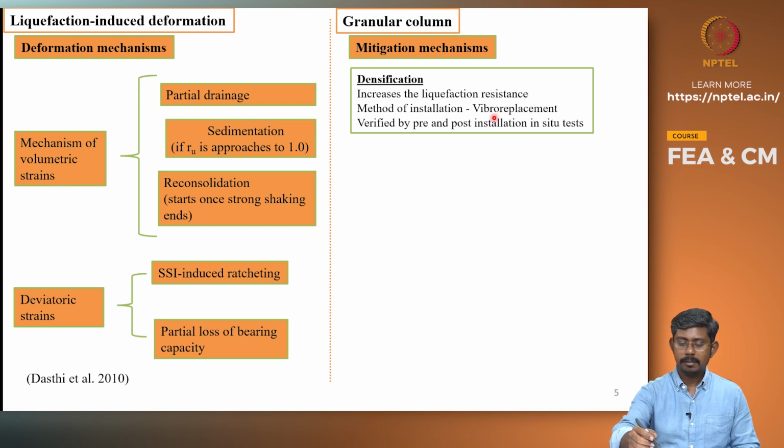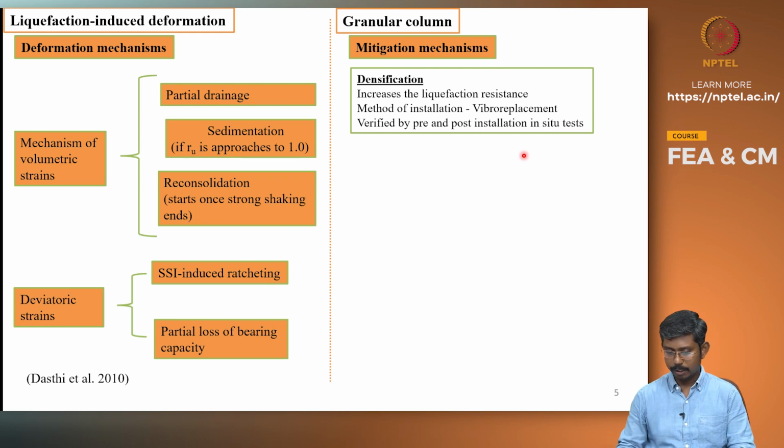In case of sand, it can be densified through the vibratory means, and this can be verified through the in situ test before the treatment and after the treatment. Say for instance, if the SPT test is conducted, the effect of densification will get reflected in terms of N value.